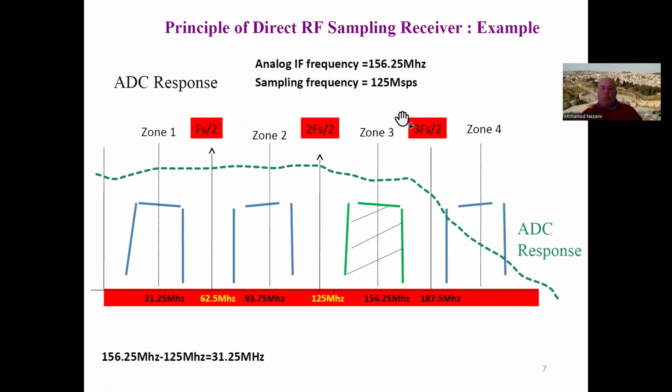Now when you digitize this signal, you are going to get the same information available at various zones as well. It does us no good to look at the zones above here, because they're just going to be attenuated and distorted. But we can pick any of these, including this one, and rotate it to baseband using a numerically controlled oscillator in the FPGA or the DSP.